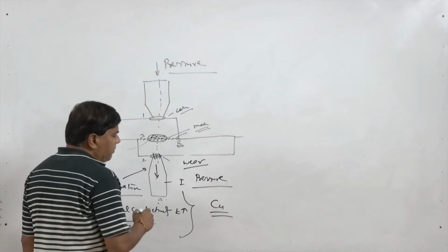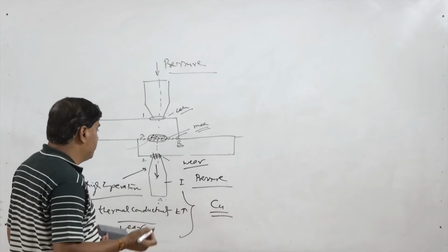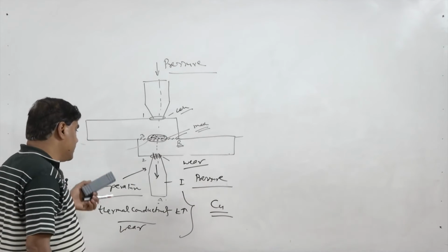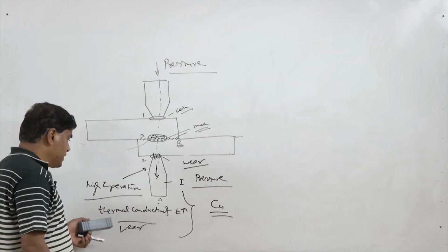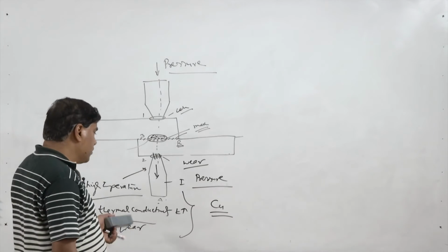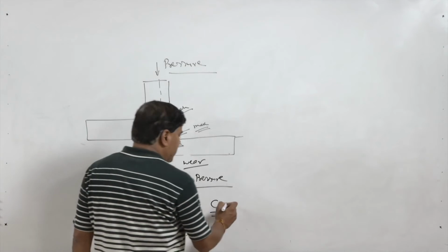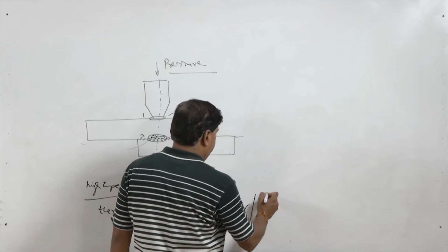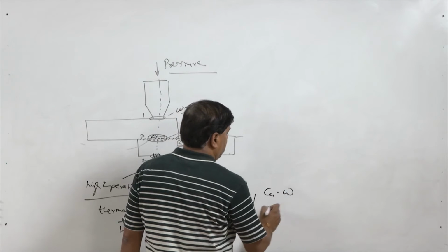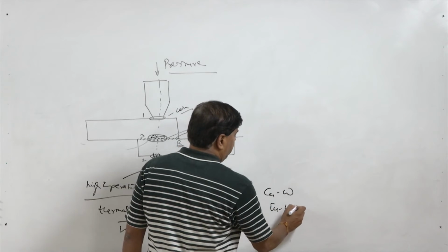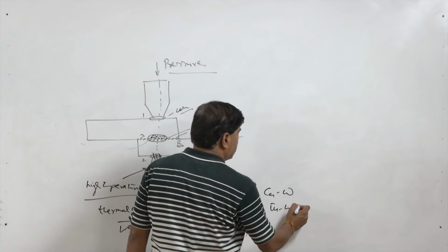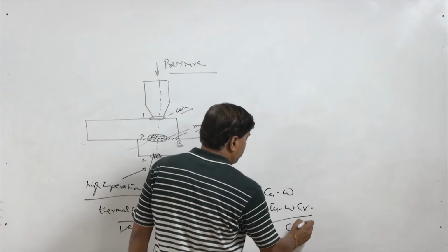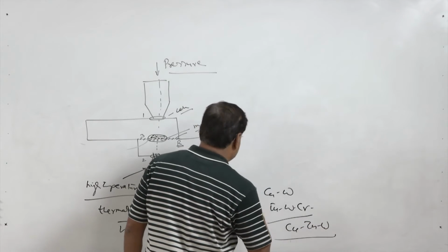These electrodes are normally water cooled also to maintain a safe temperature limit, but since they have to handle the heavy current, good electrical conductivity is needed, high temperature resistance is needed, high thermal conductivity is needed, and good wear resistance is needed. So, copper is normally alloyed with various alloying elements like copper chromium and copper tungsten; sometimes zirconium is also used, copper, zirconium, tungsten systems.